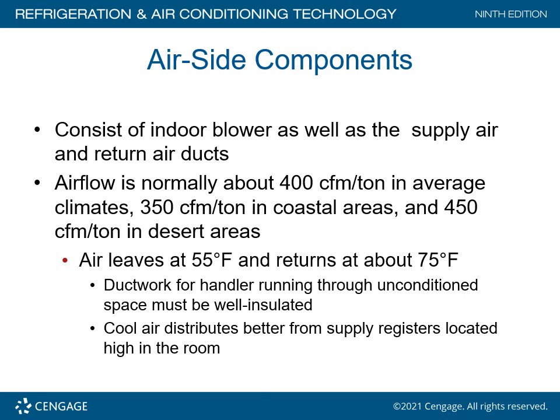Ductwork for the air handler running through unconditioned space must be well insulated. That's a no doubt. I've seen many houses where the ductwork literally falls apart after 15-20 years because of heat issues, because of the plastic deteriorating on flexible duct, and typically this means you have to replace all the ductwork. The newer ductwork that's being sold and installed in housing and commercial has a silver reflective coating on this polymer plastic, which tends to make the ducting last over a longer period of time.